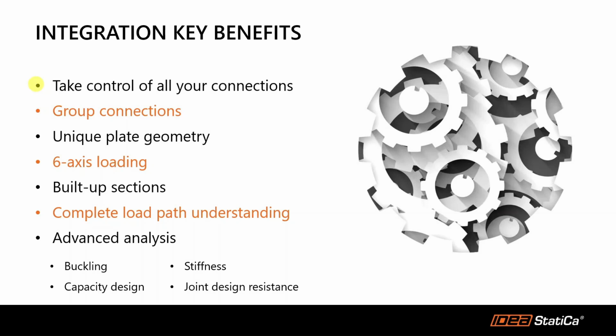Okay, so now that we have covered the entire workflow, let's go ahead and conclude with the benefits that this integration between IDEA StatiCa and RISA offers. So first, you are able to take control of all of your connections, meaning that you can have all of your connections in one place, including the simple connections and the non-ordinary connections. Within IDEA StatiCa Checkbot, you are able to group your connections, so you can model only one connection and then apply the design to the rest of the connections within that group.